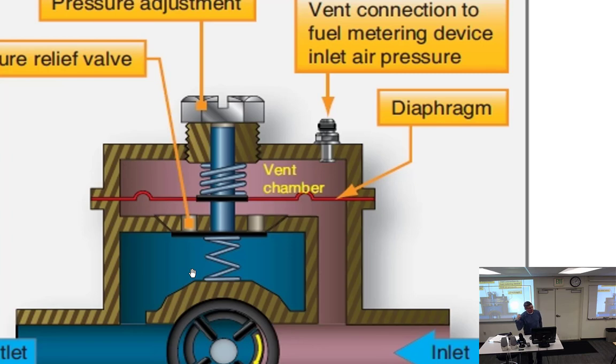We have a turbocharger. Turbocharger is slow to react. Engine sped up. Need more fuel. Now that exhaust gas is going to go around. It takes a while. Turbocharger's like, hey, we're speeding up over here. So it takes a minute. It starts speeding up. Now when the turbocharger spools up, it starts compressing more air into the engine. What do you need? More fuel. Well, thankfully, one of the ways we can do that is through this to help out a little bit.